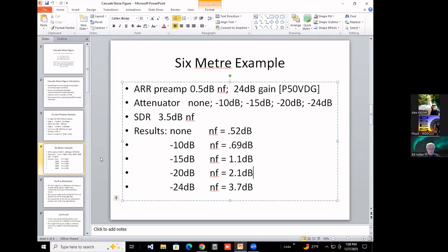So you have to switch to manual, get rid of the 10 dB pad, and maximize your gain out of the preamplifier, because the preamplifier noise figure is less than the SDR receiver. So you always maximize the gain on the front end towards the antenna and reduce, as Ray's saying, the signal at the receiver. In your case, the 10 dB is actually doing worse. So that's what my suggestion would be.